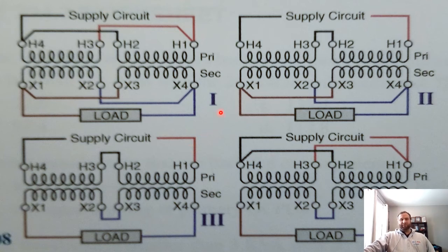So test yourself. Go back and look at 224. I believe it's 1 or 2, and understand the principles involved with buck boost transformers like this when they're configured for an isolation configuration. None of these diagrams here are an auto transformer. These are all designed for isolation right here. These are isolation diagrams.